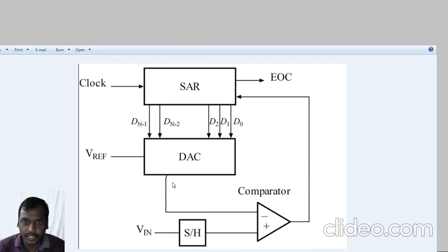So here we wrote the ADC program. So how does the conversion happen? Okay, I will explain here in a separate block diagram how it performs the internal operation. Whenever it receives the clock signal, clock signal means low to high, then high to low, like that. Here a successive approximation register is there. The inputs given are V reference voltage and V in voltage. Initially V reference is 0 volts. Here V in is, suppose the potentiometer is measured to 1 volt.